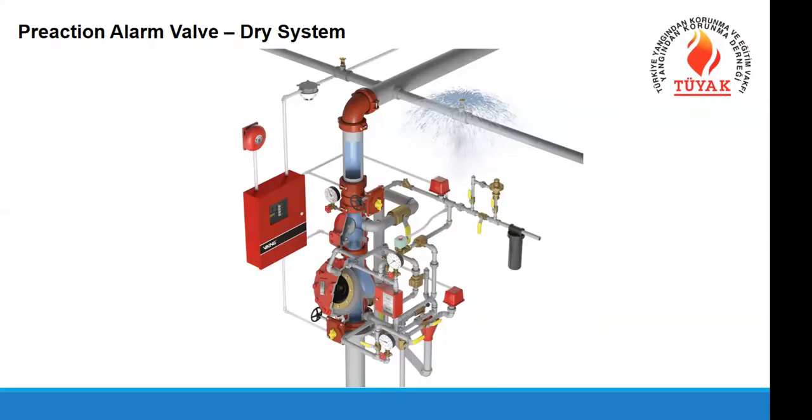The pipes are filled with pressurized air, and we don't have water inside the pipes. Just to protect the room, we are protecting the devices or material inside from accidental water discharge. So this is a kind of double safety system when you consider very special and expensive room materials.